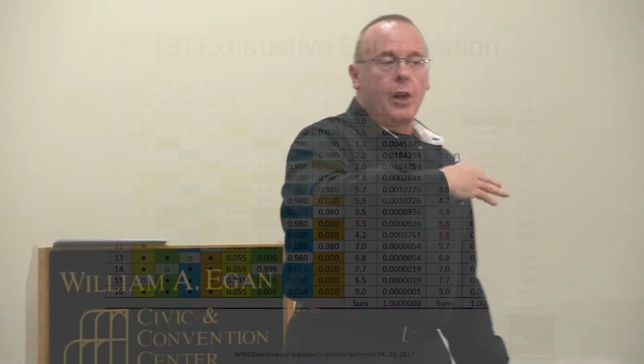So this works on the lower boundary when you only have a few fixtures and you're trying to figure out what is the peak demand on that branch. This works quite well. This also has a limitation, because as the number of fixtures increases and it's 2 to the nth power, it starts exploding.